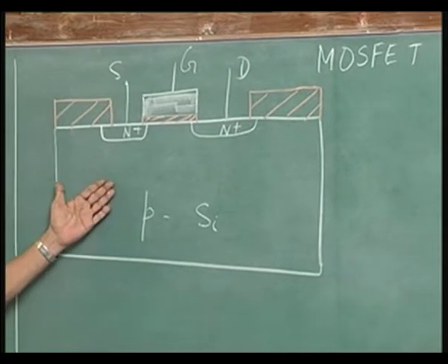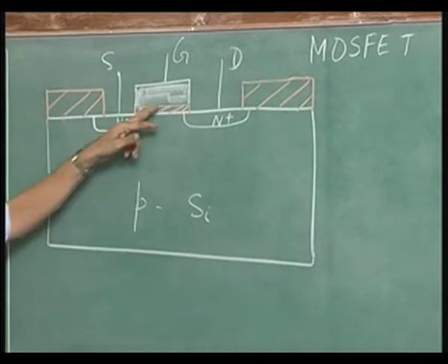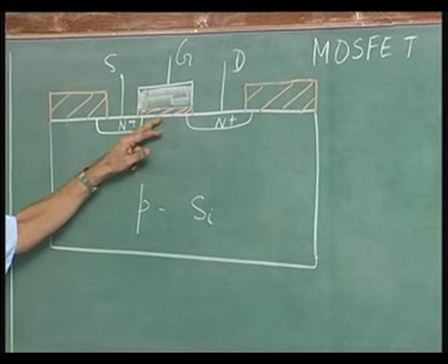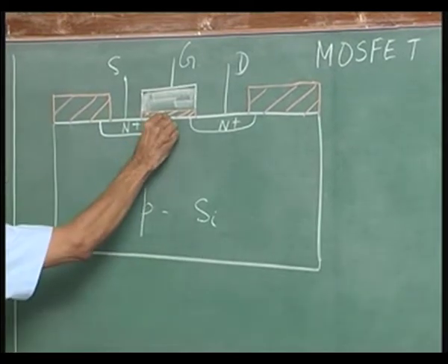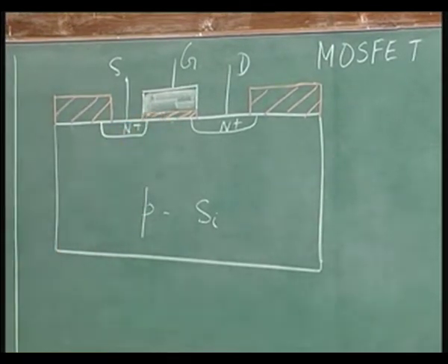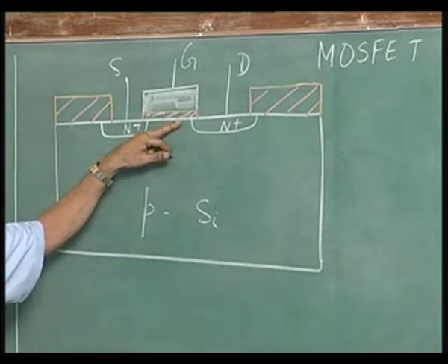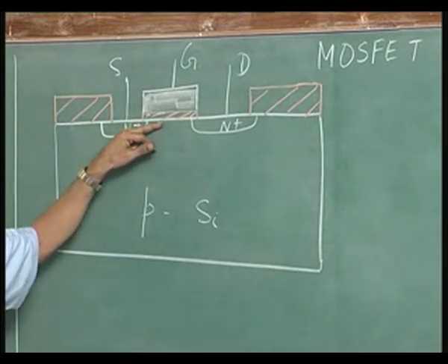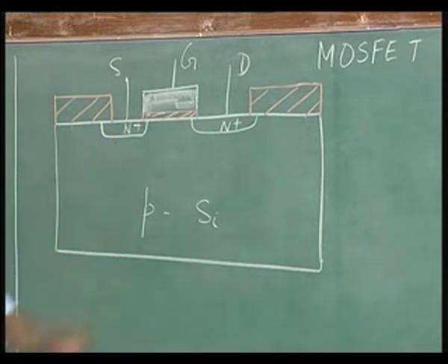We are getting excellent performance because of this oxide. The entire success is because the interface between this oxide and silicon is very clean. The charges in the oxide are minimum, that is, it is close to the ideal insulator, not exactly ideal. What is an ideal insulator? Zero charge within that, and a very clean interface. There are no charges staying at the interface, that sort of thing.